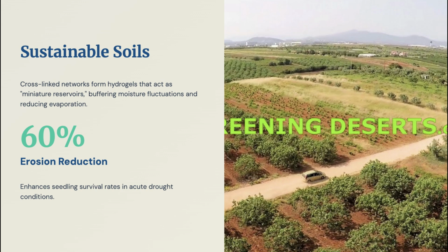What we observe through empirical field data includes a substantial reduction in surface runoff, decreased soil particle detachment, lower tailwater turbidity, and a mitigation of nutrient leaching. While the exact scope of these reports varies based on soil classification, field slope, and rainfall intensity, proper management has verified a 20% to 60% reduction in soil erosion and runoff cloudiness.